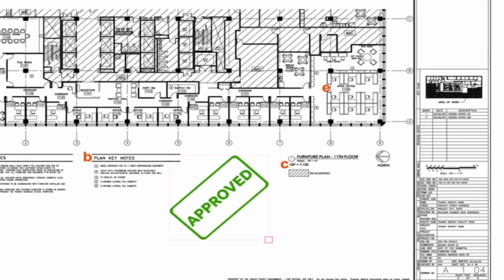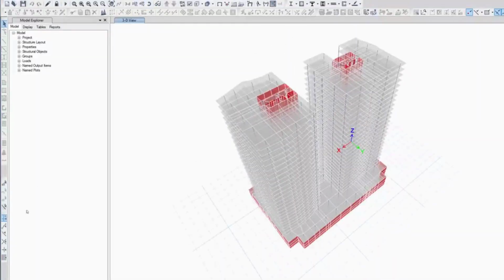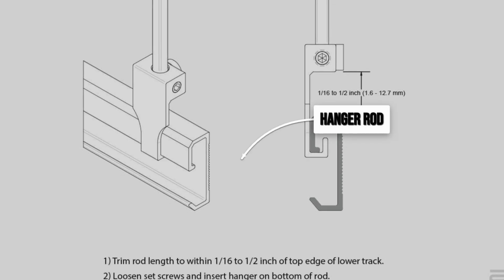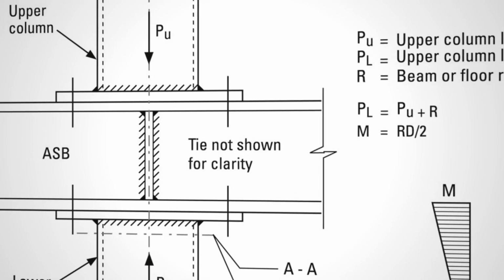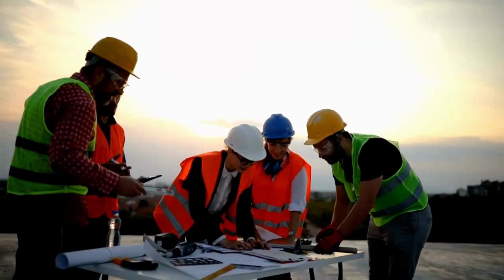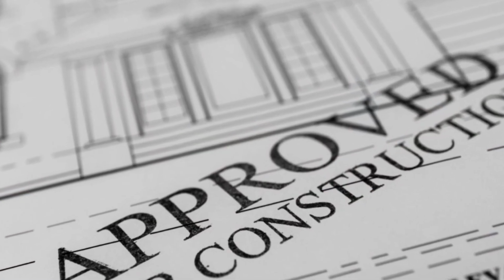Professional responsibility in structural engineering extends beyond checking calculations for individual parts. When the hanger rod detail changed, the increase in load at the fourth-floor connection exceeded the 10% threshold that should have triggered a full system review. Yet no reanalysis was performed.